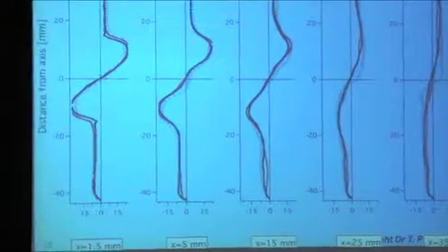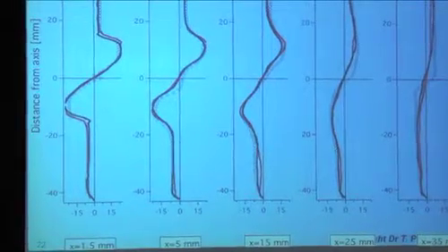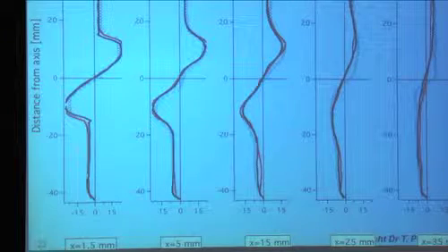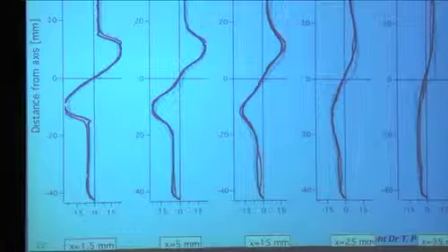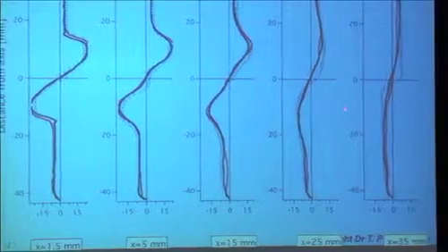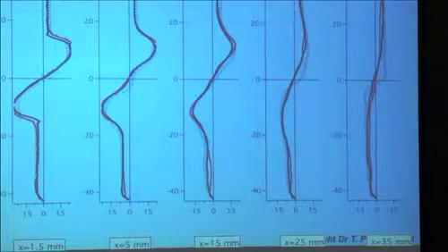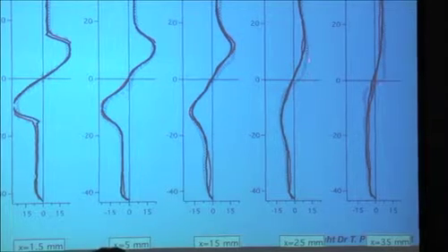This is the azimuthal velocity. So this is the rotation of the flow like this, you know. And again, you can see it's large, 15 meters per second. This is just in front of the swirler. So this is where the swirler is making the flow turn. And you can see that the comparison with the experiment is quite good, except here, where certainly the experiment is wrong.